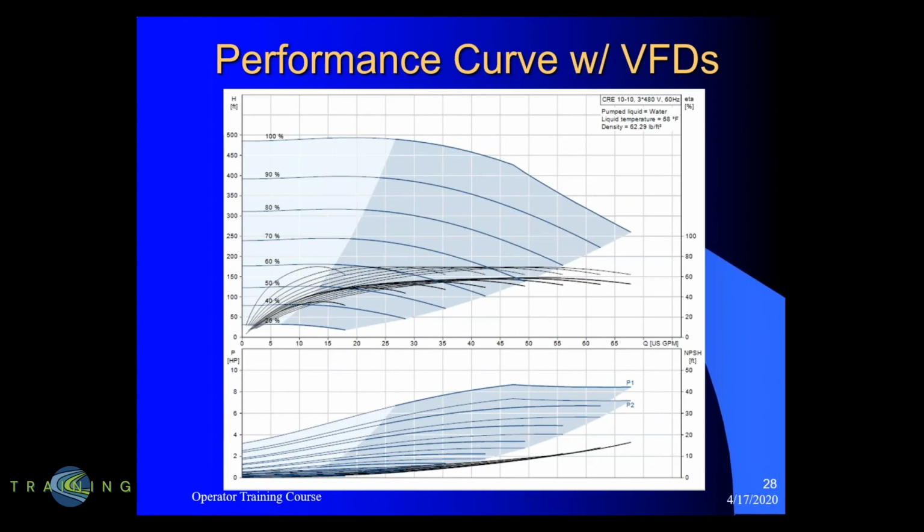One of the ways that we hit the demand of a community is by putting in a booster station and trying to maintain downstream pressure. So if you have a new community on a hill somewhere, a subdivision, we want to make sure that you always have somewhere around 60 pounds of pressure in your faucets. So what we do is we put in a transducer. The transducer provides feedback to the control system and changes the speed of the pump so that we're maintaining a downstream pressure, which will equate at the end of the line to a consistent pressure.